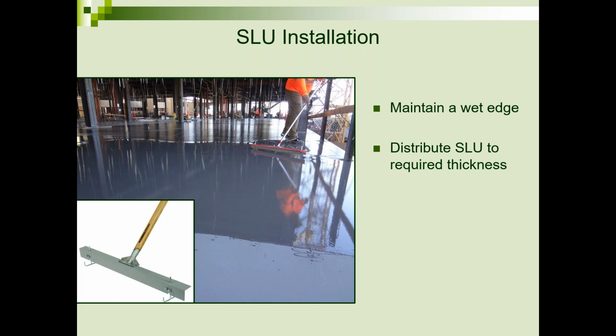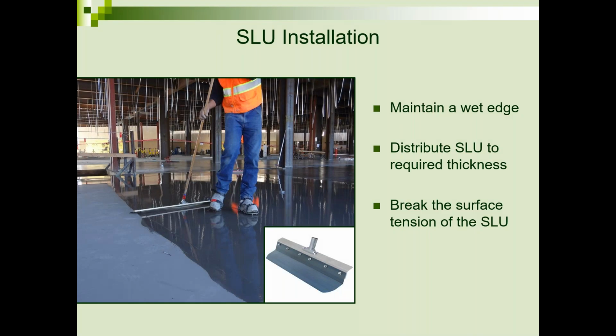Once the material is poured or placed, you use a gauge rake to distribute the product in generally a uniform thickness. Once the gauge raking is done, the contractor will typically run over the surface with a paddle. The paddle helps distribute product, but it also opens up the material. So if there's any air that's been trapped in the underlayment during the mixing process, it allows that air to escape, smooths the surface, and gives you a nice mirror finish that's very important or expected for that installation.